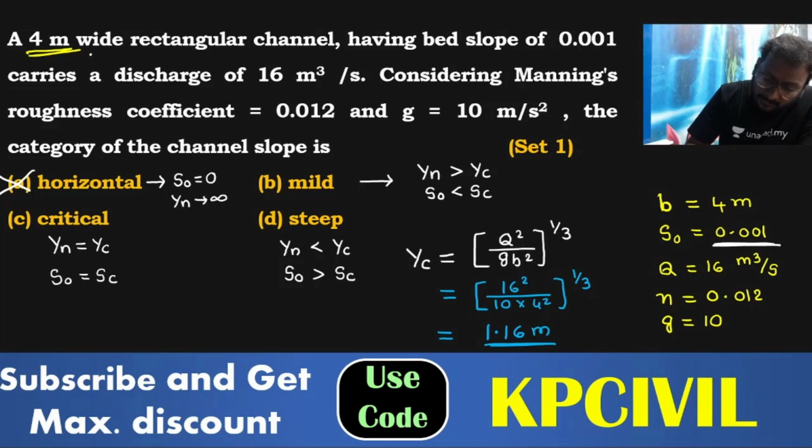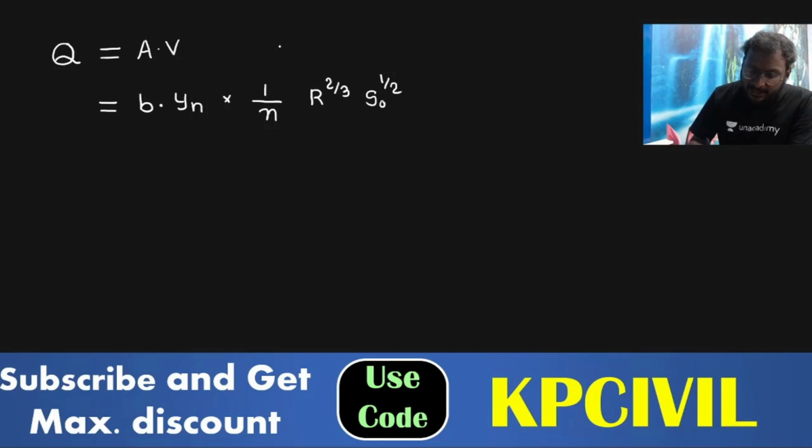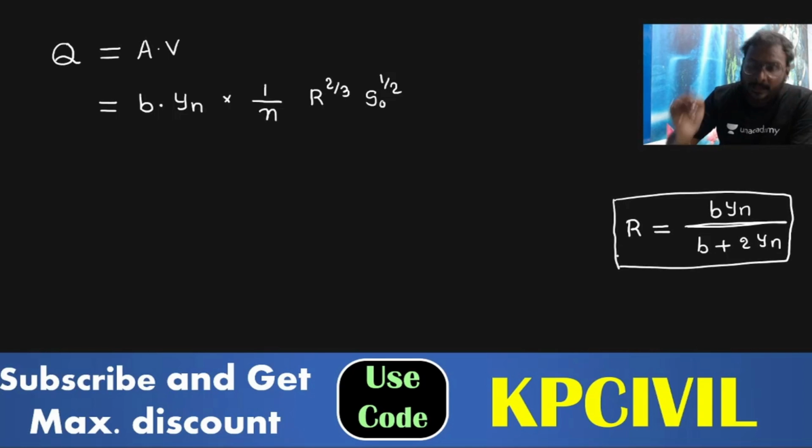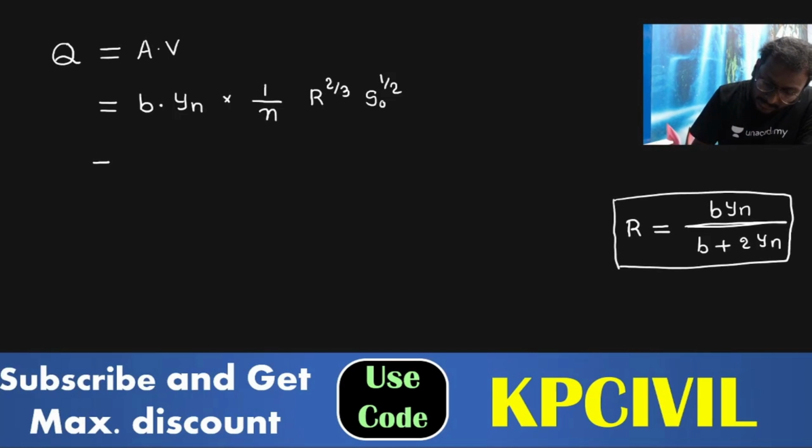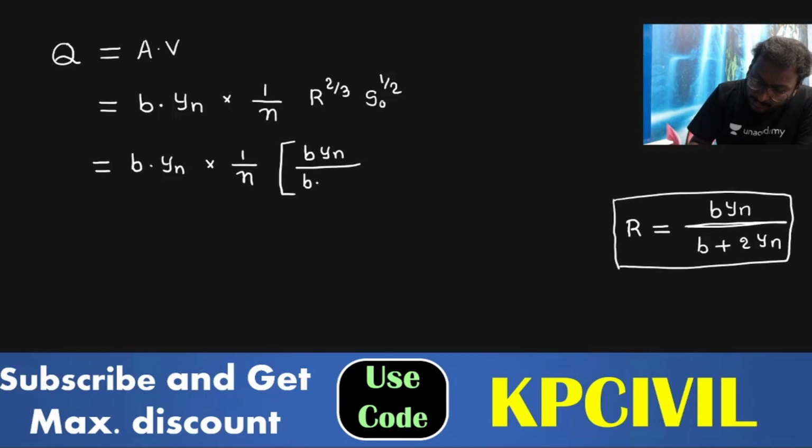And it was mentioned as a wide rectangular channel. For a wide rectangular channel, what is R? As per channel geometry, hydraulic mean radius is equal to area by perimeter, wetted area by wetted perimeter, A by P. Area is B Yn, perimeter is B plus 2Yn. Now I am substituting here: B Yn into 1 by n, then in place of R, B Yn divided by B plus 2Yn, whole power 2 by 3, S naught to the power 1 by 2.